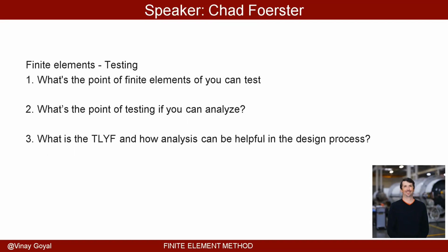You can estimate loads. You can build a test stand to apply those estimated loads, right? Because you can hand calc all this stuff on an Excel spreadsheet. And you can say, this is the moment, and this is the shear, this is the temperature, and I think I'm going to have this load case here at this event, this load case here. But really, for these complex aerospace systems you're going to want to build a Craig-Bampton model, or a coupled loads analysis model. It doesn't have to be a reduction of the model.